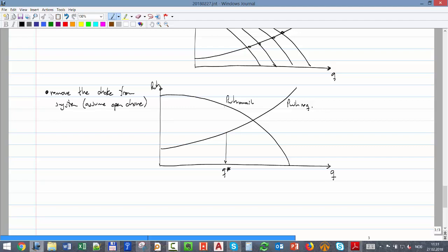Yeah, it's just the difference, because these two curves tell you I have more energy than what I need. So I need some element to dissipate that energy, to break that energy, bring it down to this level, to this value. So I need my choke. This has to be the delta P of my choke.